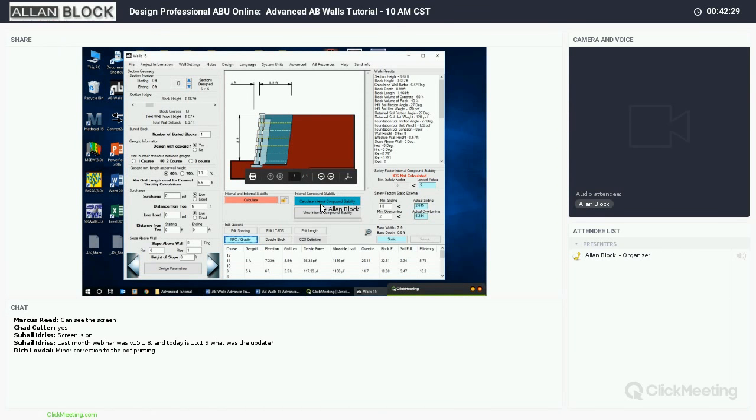One of them I outlined already, where a new roadway is coming in. They don't mind the grid down below, but as soon as they have their curb gutter, that kind of stuff, they don't want anything protruding into this. So we've just gone into a no fines concrete on top to get around some of these options.